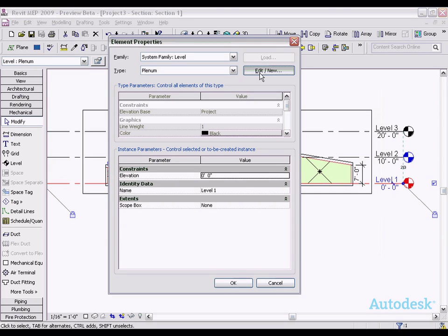But basically we have a level that it's hosted at, and then the top boundaries of that particular space or room. So what that means is we find a two-dimensional cross-section, and then we'll extrude that cross-section vertically until we hit bounding elements. So in this case we can see here that we have a room that is set to have an upper limit of the third level here, but since it is extruded up and hit this roof as a bounding element, it has stopped its extents right there.